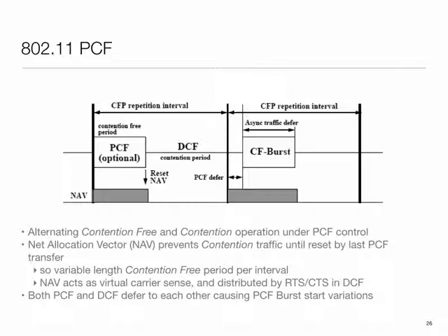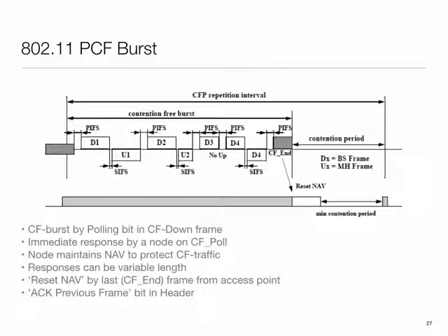And then the remainder is set aside for the asynchronous traffic that I just mentioned. This begins to give the possibility that a node could go to sleep, because if it is doing some very periodic traffic, it will wake up only during its assigned times when it is actually expecting a packet, and otherwise go to sleep. So sleep management begins to come through this.